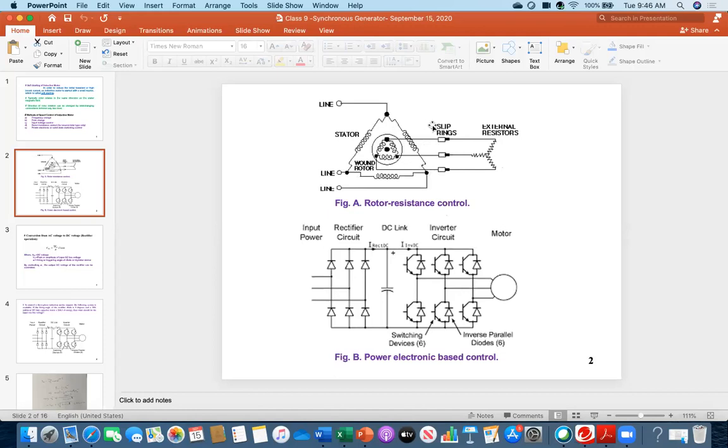Those slip rings are also moving, but the black part is called the brushes, carbon brushes. This means with the external resistors, the carbon brushes are static, while the slip rings are moving and just coming in contact with the brushes. Consequently, the impact of resistance goes into the rotor circuit.